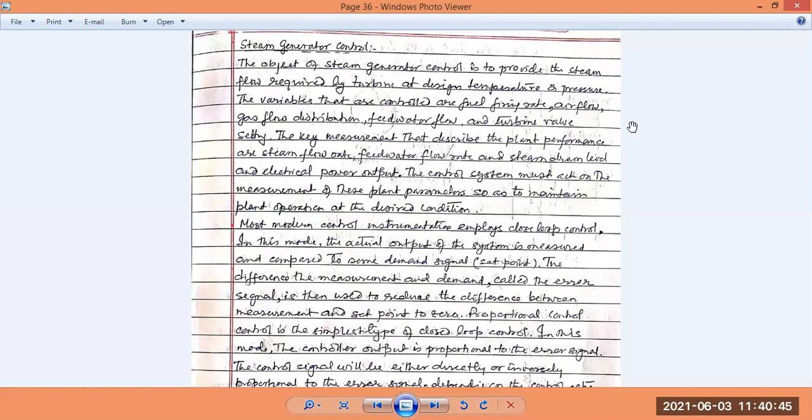Turbine is run by the injection of steam at a definite high kinetic energy. The huge heat energy of the superheated steam will be converted by running through the nozzle into kinetic energy, which will be injected over the turbine itself, and it will get the required rotation of say 6 or a few thousand RPM, as per your design requirement, design pressure of your system itself.